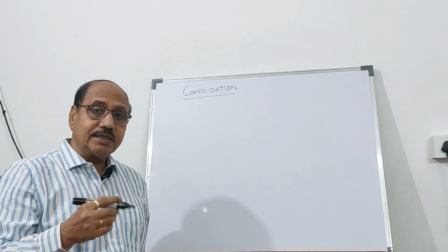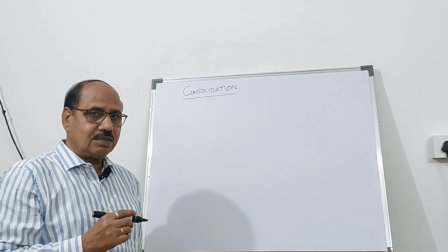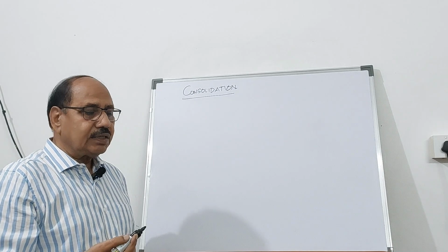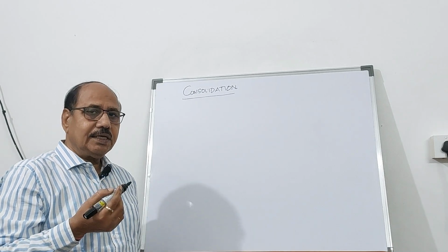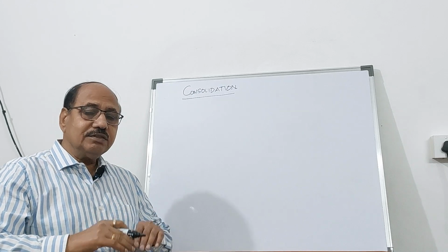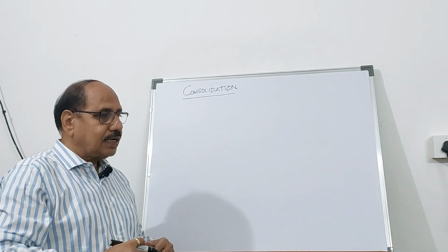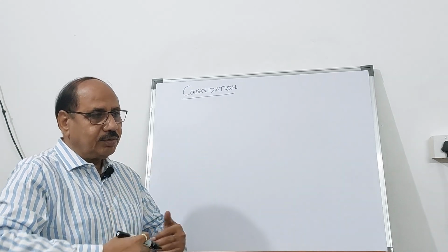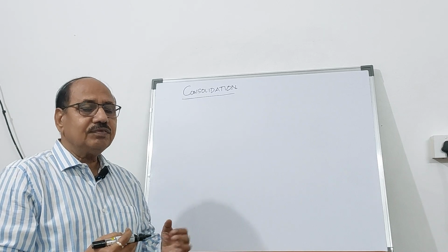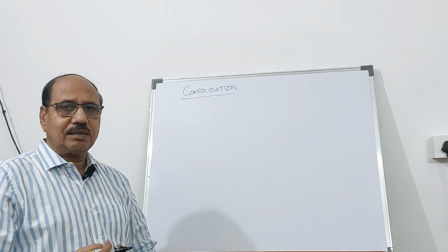Because the hydraulic conductivity of the clay soil mass is quite less, it takes a longer period of time. And therefore, the loaded soil mass goes under consolidation after dissipation of the pore water. As the pore water dissipates over a period of time, the soil is going to rearrange itself, the void is going to decrease, and therefore this leads to settlement.